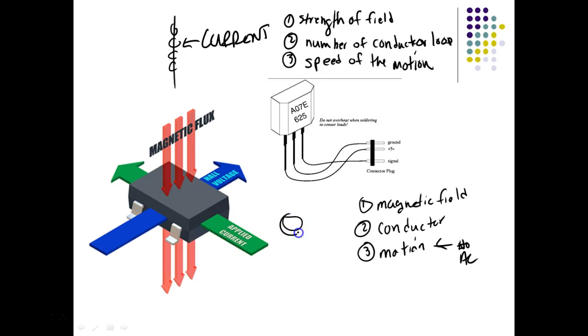It's nothing but the secondary of a transformer. They're called CTs, current transformers. We run a wire through it, and then we measure the strength of the field. And these are used in industry all the time to measure current without breaking the circuit, right? But what's the problem is this has got to be what? It's got to be AC. So clamp-on ammeters will not measure DC in the clamp. They'll measure AC in the clamp.